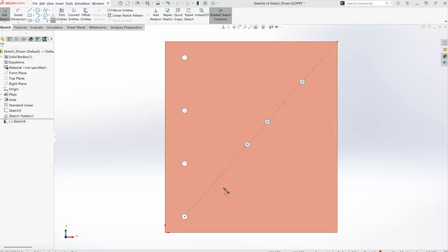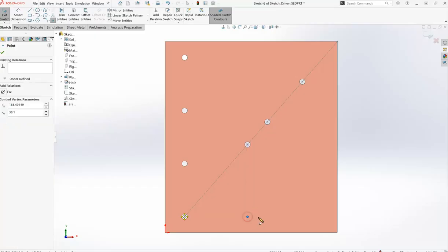Okay, we're going to create 4 more points, and we're going to make it look like the book. This one we're going to use inference lines, and so I've got point selected, and I want to come off this one horizontally, and it looks like in the book that other one comes off that hole vertically, so we'll put one there. And then the other one is also horizontal, but it looks like it might be vertically aligned with this one. And so if we hover on this one and bring this inference line down, we should be able to get a cross point, put one there.